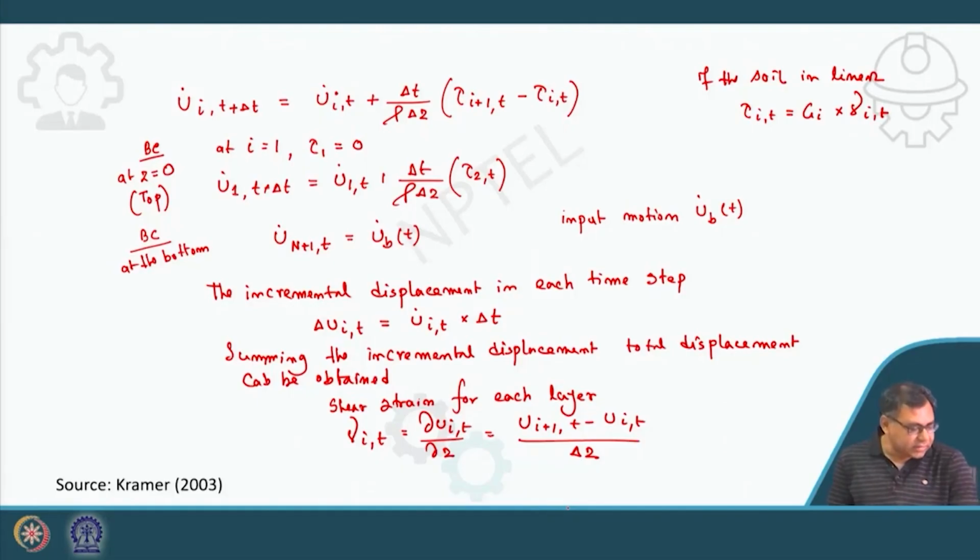So in such a case, the cyclic stress strain relationships are used, or we can use an advanced constitutive model to get the proper shear strain of the soil, or to simulate the nonlinear behavior of the cyclically loaded soil. So there the stress strain history is also required. For the linear case it is not required, but for the nonlinear case the cyclic stress strain relationships are required.